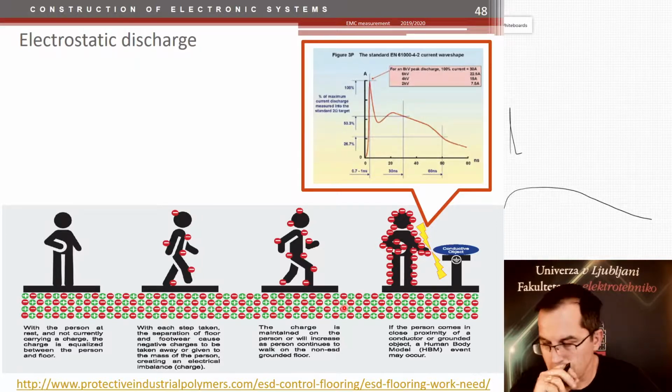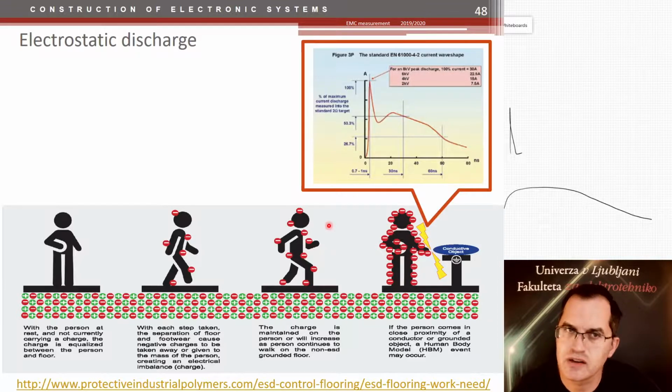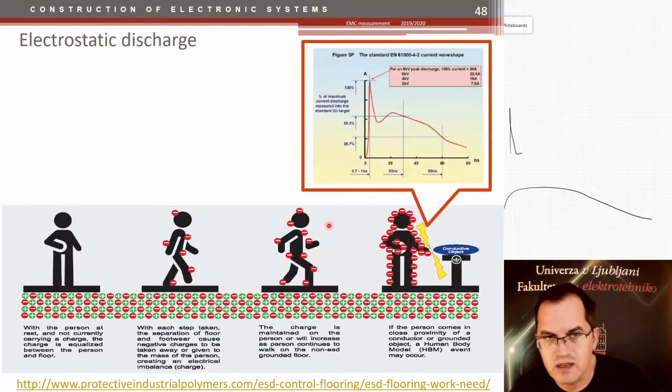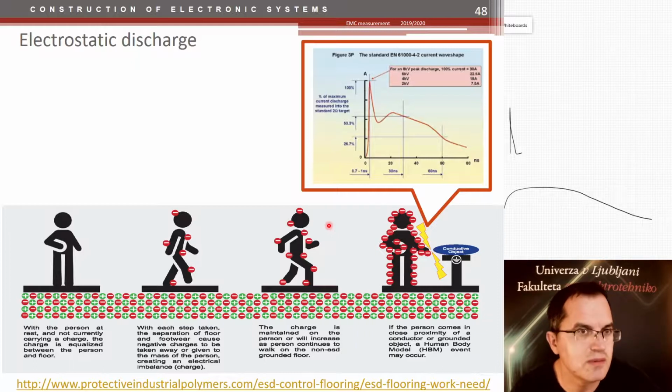Now, the problem is that in these manufacturing facilities, if you don't keep strictly to the rules, you can get fired, because if the electronics you're handling receive an electrostatic discharge pulse, they might still work, but not for a long time. Maybe they would work for 5 years instead of 10 years, or 1 year instead of 10 years. So that's a problem, and you have to be really strict with these rules.